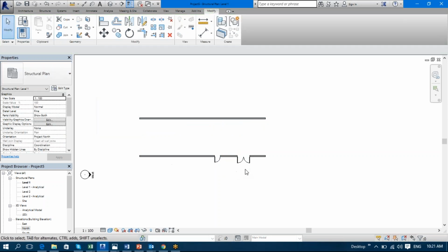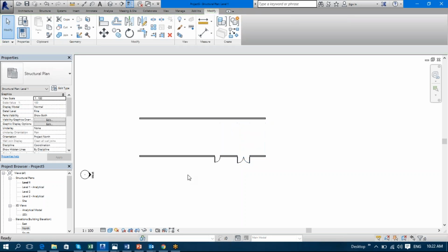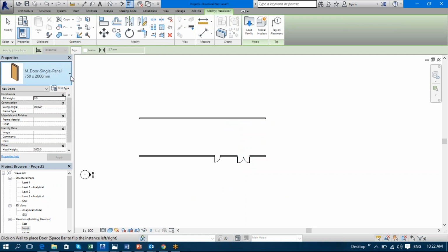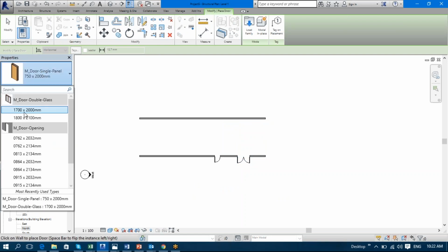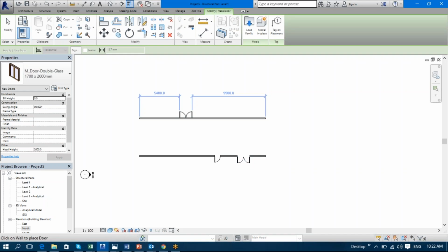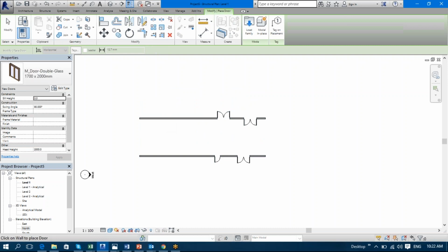Now what happens if I want to create this kind of door so many times? I have to type DR on my keyboard, then go to this type selector and select this type of door, and then I do this, right? Now I can create this part. But after a time I want these doors to be created here. Now what should I do? Again DR.